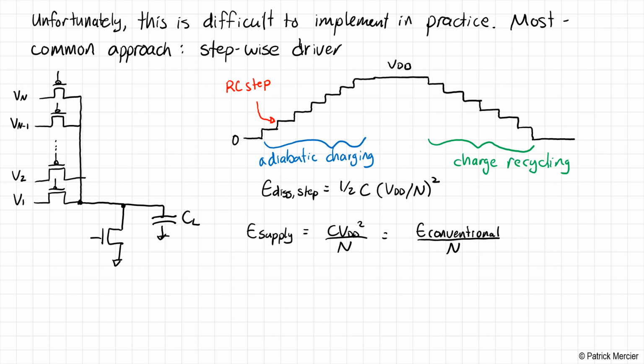So that was actually quite an exciting result. Now, the other thing that you have to think about here: you are intentionally slowing down the edge rates. So as a result, your edges here are slower. That means you must operate your circuits to be slower. And that is a major downside of this approach. Okay, so please do keep that in mind. Adiabatic circuits, by their very nature, must be slower than non-adiabatic circuits. So that is definitely a trade-off that comes into play here.